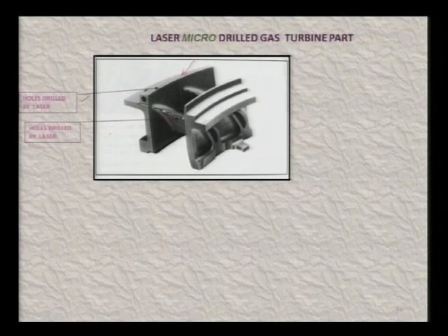And there are holes in an inclined direction here on the other side, and at the bottom also, if you see, there are small holes. Here also on the sides you have holes, and all these holes are being used for cooling the turbine blades, because the temperature of these gas turbine blades is around 1100-1200 degree centigrade, and at such a high temperature they cannot work unless you have efficient cooling, and these cooling holes are made with the help of the laser beam drilling operation setup.